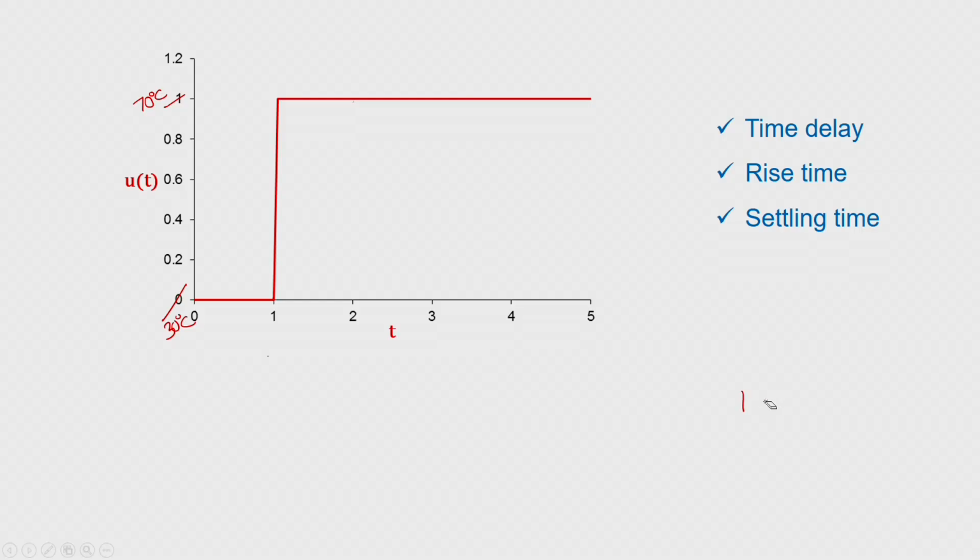While measuring the body temperature, if the body temperature is say 104.3 degree Fahrenheit, then we may choose a band of something like 0.1 degree Fahrenheit. That is, once the temperature becomes restricted between 104.2 and 104.4, we may say that it has attained the settling time, it has settled within a 0.1 degree Fahrenheit band, and now we can use this particular reading for further processing.